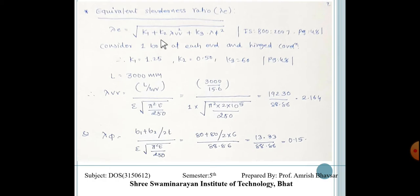Now, as we know it is eccentric, that's why we have to find out the effective lambda, and for that we have the equation: under root of k1 plus k2 into lambda vv square plus k3 into lambda phi square. It is given on page number 48. Consider one bolt at each end, hinge. We can get the values of k1, k2, k3 from page number 48. We have the length, that is 3000.